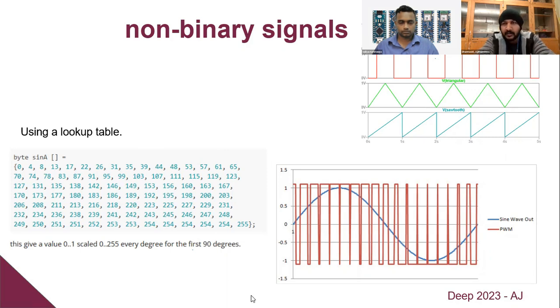And in the right part, we can see the sinusoidal wave in blue, and then this other curve in red, which says PWM. I think we're going to talk in depth about that in a minute. So what's really happening here is we are creating the sinusoidal wave by using just PWM signals, turning the pin on and off.